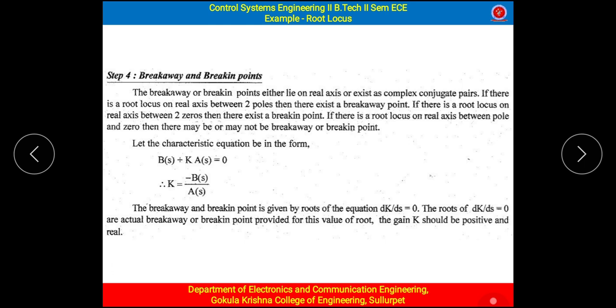That particular point where the root locus branch is coming out of the real axis, we call it the breakaway point. Similarly, when there are two zeros and 2 branches coming either from poles or infinity and reaching these zeros, if the directions of these branches are exactly reverse, then they will join. They will break in to this particular real axis. That time we need the break-in point.